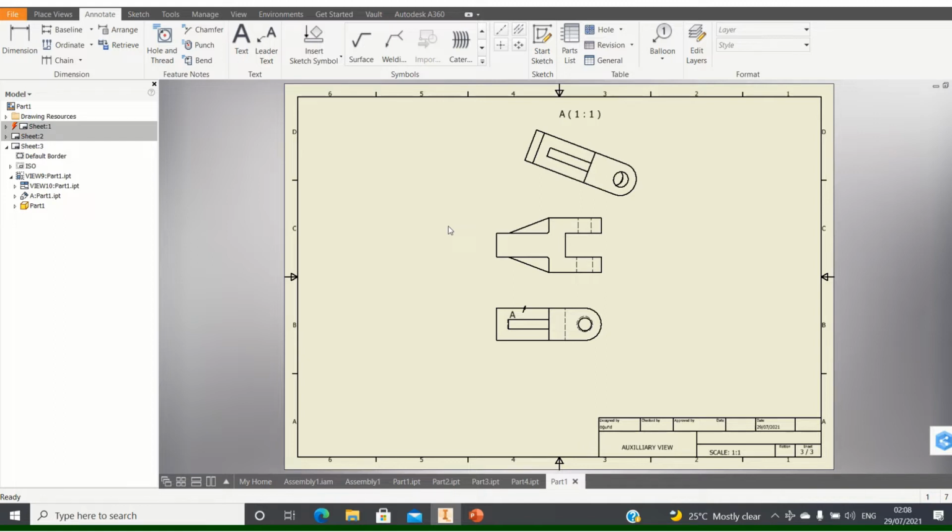So if somebody is going to produce this drawing, the machinist or the technician requires the working drawing to produce that component adequately to the required dimension. So that's why we give detailed attention to the working drawing. Now we want to conclude our working drawing by looking at sectioning. There are times when we need to show some intricate parts or hidden parts. That is where sectioning comes in. It shows us some parts that naturally cannot be seen when looking at the object. That's why we look at sectioning.